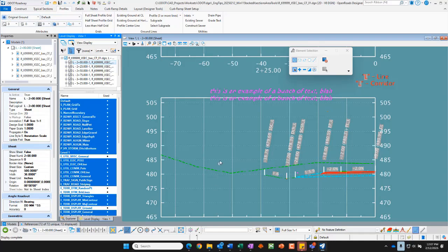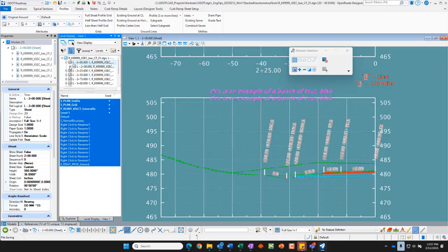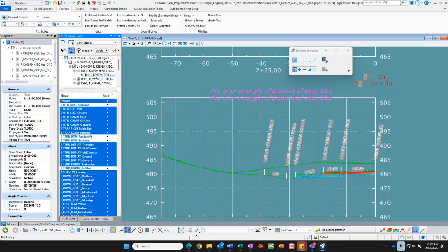When in survey we build the terrain, we want to see triangles, we want to see all this different stuff. So we have a working feature definition that we use, and the surveyor should set the existing ground terrain definition to one of the existing either contours, existing triangles, and then that sets the profile display correctly. So there can be an issue with that.